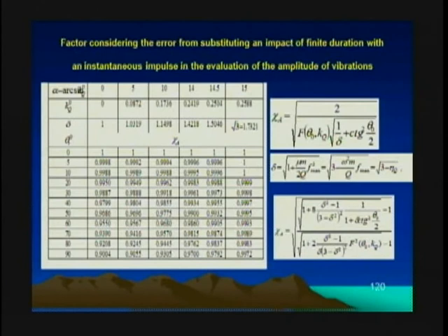But also take a look. When it's 1, you have pretty much the same results that we obtained for linear systems. But at the same time, if we go in the horizontal direction and see how the degree of nonlinearity affects these factors, we will be pleasantly surprised that a significant increase in the degree of nonlinearity, a highly nonlinear system, still enables one to use a load of finite duration, and it should be treated as a static loading, because if the natural frequency, because of the level of this loading, is very high, this loading is static.